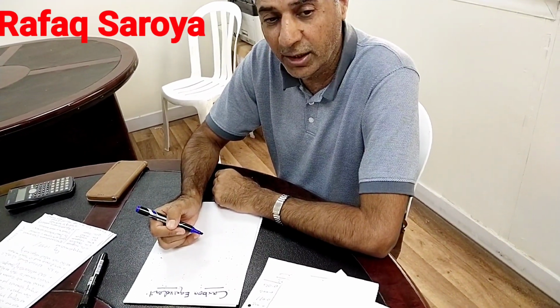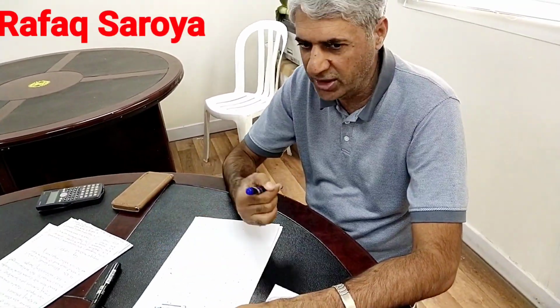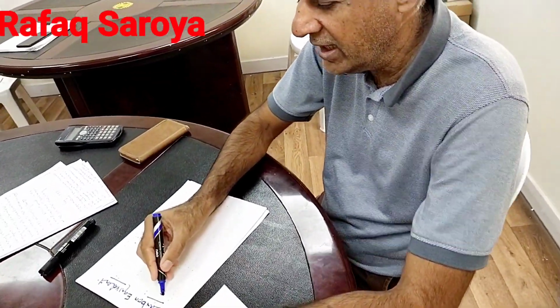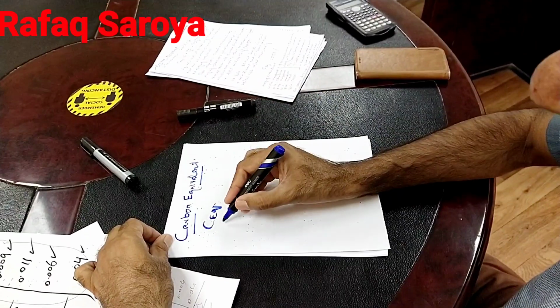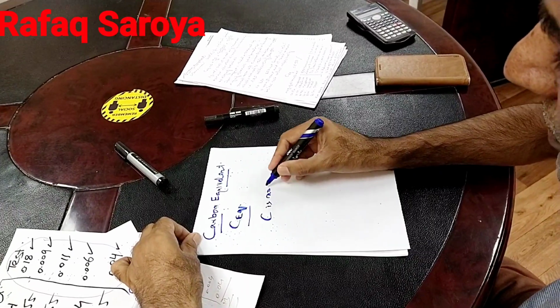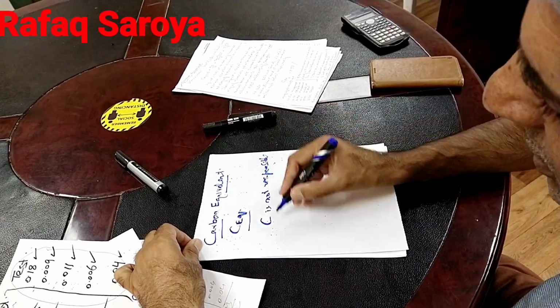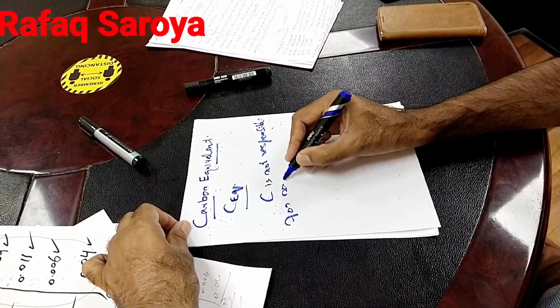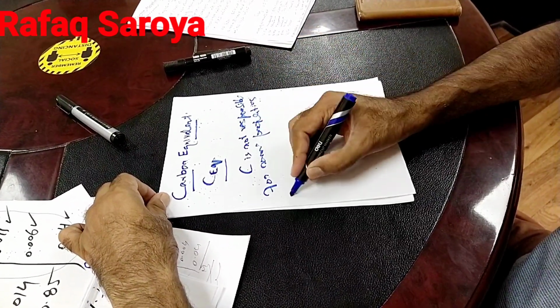We are studying the other very important chemical property for our mild steel, known as the carbon equivalent. Before I start explaining it, it is represented by CEQ. This carbon equivalent actually gives us one proof that carbon alone is not responsible for some properties of steel.